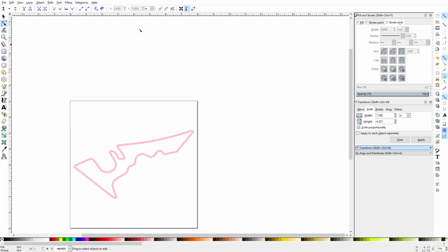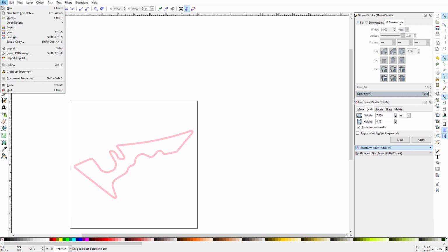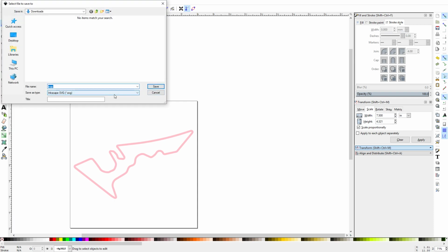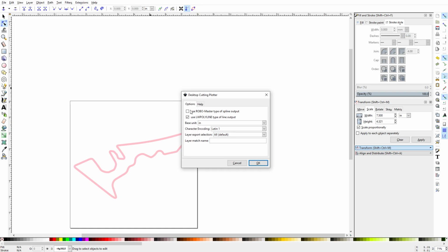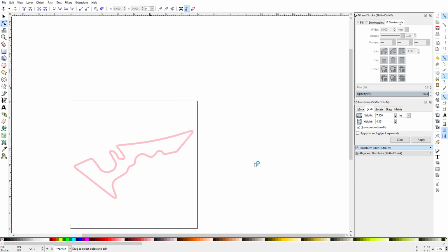It's looking nice, so now I'm going to export this as a DXF. So just go to File, Save As, DXF. These are the options I found work best. I forget what's default. Don't forget to set the units to whatever we're doing, and then select OK.